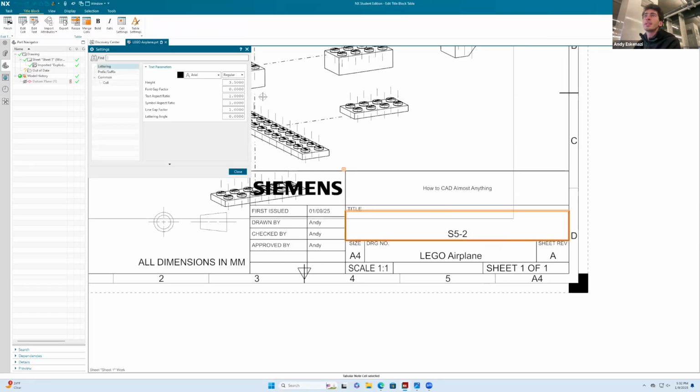And then if you click in settings, you can go to the cell, make it top center, middle center, lettering. Let's make that 9. Actually, drawing was gonna be a spine of this. Yes, this will be fine.